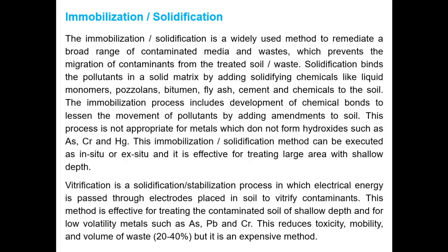Next one is the immobilization or solidification. The immobilization or solidification is a widely used method to remediate a broad range of contaminated media and waste, which prevents the migration of contaminants from the treated soil or waste. This technique has been used to treat radioactive waste and hazardous waste since 1950s to improve the soil for subsequent construction. Solidification binds the pollutants in a solid matrix by adding solidifying chemicals like liquid monomers, pozzolans, bitumen, fly ash, cement, and chemicals to the soil.